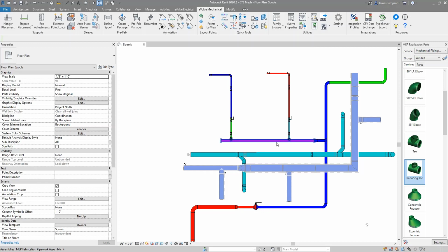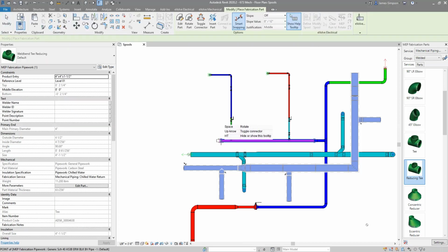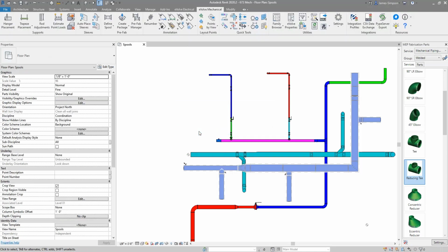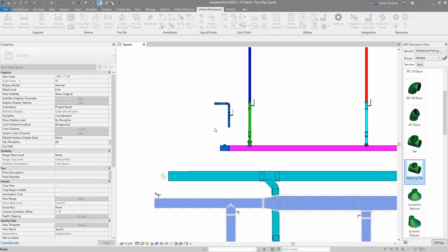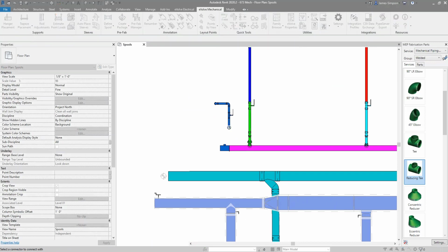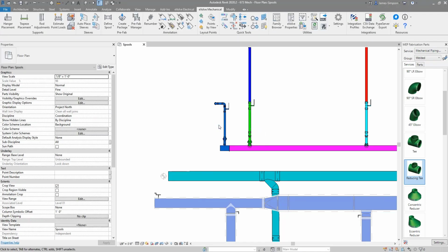And we can actually accomplish this quite easily in eVolve using a little bit of creativity. So I'm just going to make a quick example here. First thing I'm going to do is add in a reducing T, as well as add in some content that I kind of made on the fly. And I'm going to use the connect tool just to connect this super quickly. And there we go. So now we have our example.